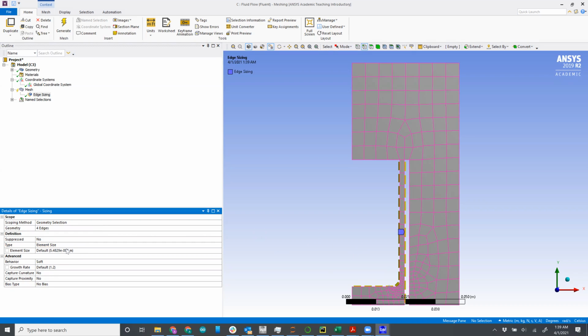Apply, there we go. For element size, it will be 0.123455. See if that works. That looks good. And in meters here, even though everything else is in centimeters, make sure that this super tiny mesh size is in meters.